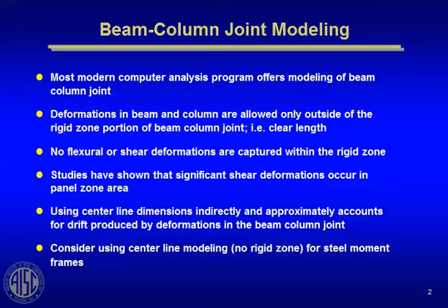And of course, when you design a concrete frame, you have these same issues that you have to deal with. How much of the joint do you take as rigid and how much do you take as flexible? But we won't get into that here. This slide also just shows that you can, in a lot of this modern software, input the properties that would allow you to model the panel zone deformation if you so desire.